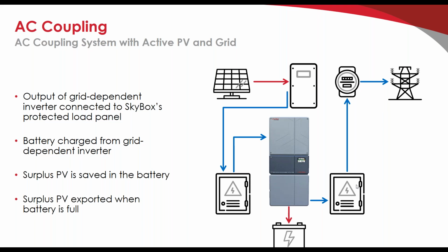You can take one Sunny Boy and connect it to either a Radian or a SkyBox. If you had two of them, you would need to have two Radians. You couldn't get that job done with two SkyBoxes or three SkyBoxes. It'd be two SkyBoxes today with the current firmware.